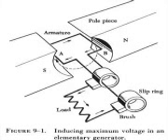However, when the field is distorted, a voltage is induced in these shorted windings and sparking takes place between the brushes and the commutator segments. Consequently, the commutator becomes pitted, the wear on the brushes becomes excessive, and the output of the generator is reduced.